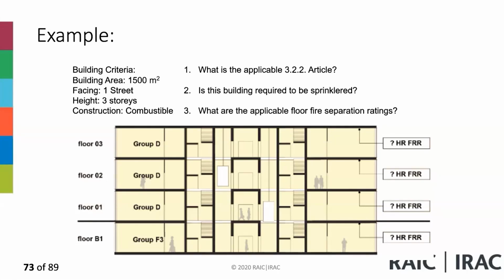Okay. Another question is for a subsidiary occupancy. For example, I have a mess hall in a residential building or condo. Yeah, it's subsidiary. Do they have a separation required too, or is it not required? No, it's not required, but you've got to take a look at the corridor serving assembly areas. But it's not a separate major occupancy.